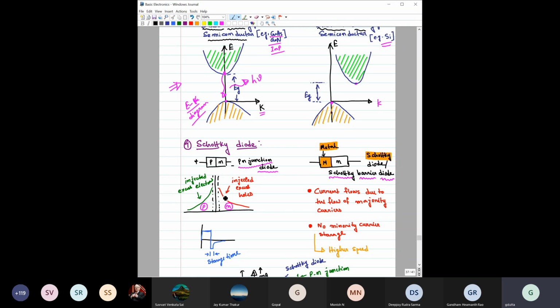So this will be the profile of this. And then also you have seen, if we now immediately reverse this polarity, make this negative and make this positive, then we have seen this current conduction through this PN junction will not stop immediately, right? It will take some time, that storage time and then decay time. So you have to give some amount of time before which this PN junction can turn off completely, right?